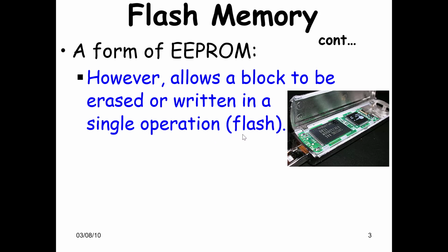So what happens is that in a flash, you can write or erase a full block of data. So basically, the idea is that you can't access data in, let's say, small chunks of 4 bytes or 8 bytes, but essentially you access data in bigger chunks known as pages, which can be as much as a kilobyte. So that's why you would need a piece of DRAM along with the flash. And also the other thing is that you can read at the granularity of pages. You can also write, but once you have written, you cannot rewrite.